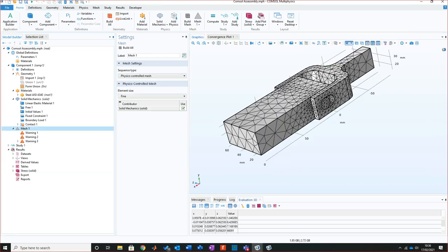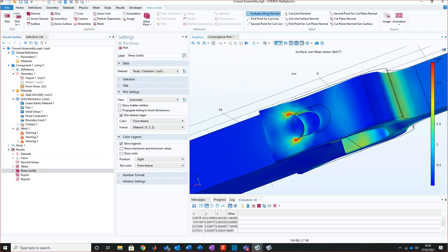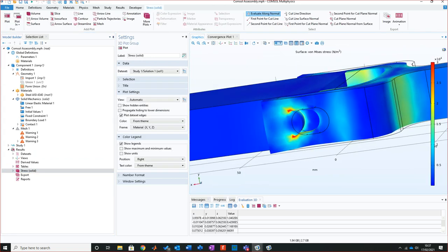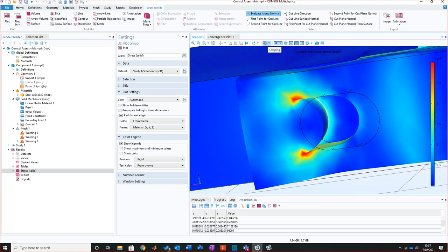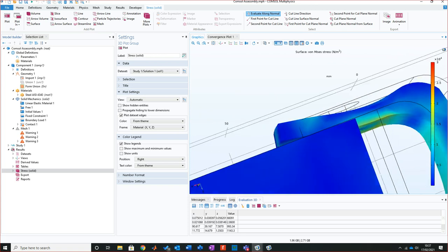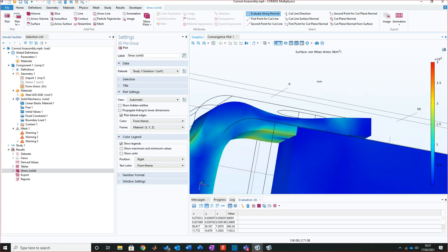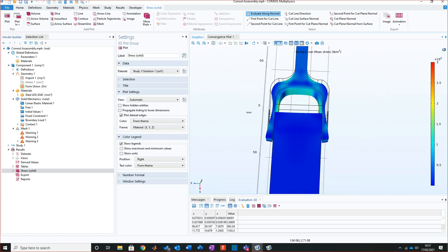So onto this mesh, it's relatively fine. It is heavily concentrated on these areas. If you look here, it does concentrate itself quite nicely onto these areas, and it's quite large, if I'm honest, onto them key point areas. My question, though, is, is it a true reflection of what we should be getting? Now, you can see there that it's deflecting on the inside.